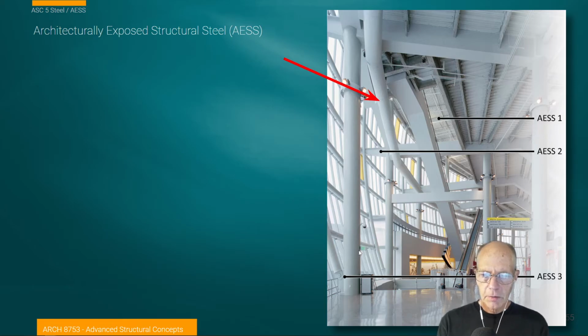So here we have this beautiful structural steel facade, and we have things that are very close where the eye makes contact. So we have this pinned connection at the bottom of this assembly, and the quality of that finish of that element, because it's very close to us, we can see it very easily, needs to be higher than things that are further away. So this idea of decreasing level of specification depending how far the viewer is from that element.